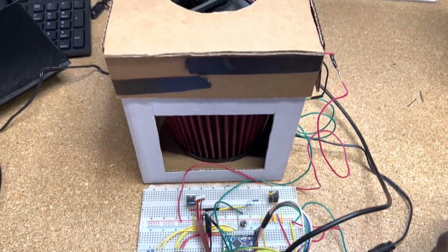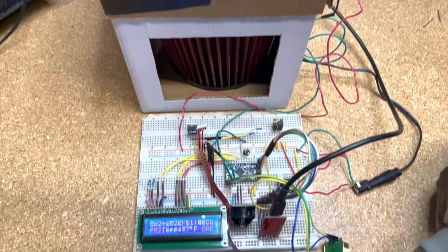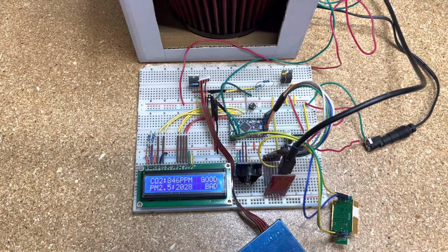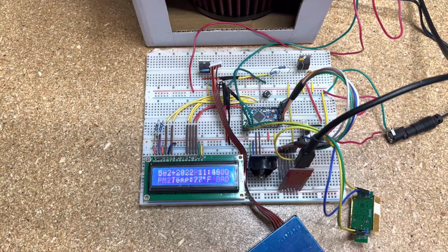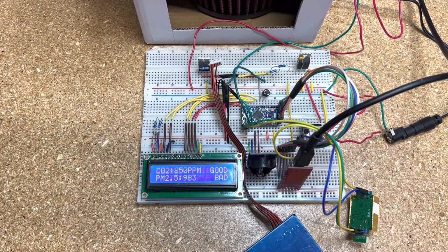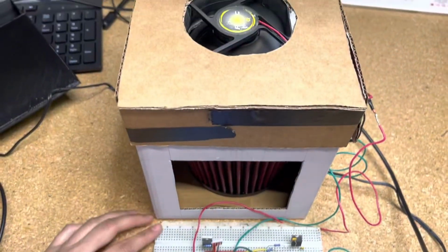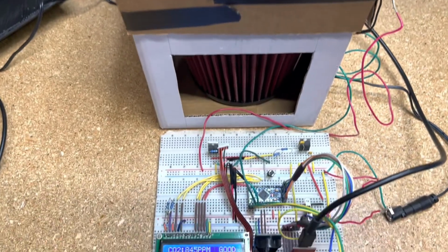In the event that the carbon dioxide values surpass the recommended threshold level of 2000 ppm, the screen will be interrupted by an alert screen that will remain visible until the carbon dioxide levels have decreased below the threshold. In a similar manner, whenever the recommended threshold level of 35 micrograms per meter cubed for the particulate matter sensor is surpassed, the filter's fan will turn on until the sensor values fall below the threshold.